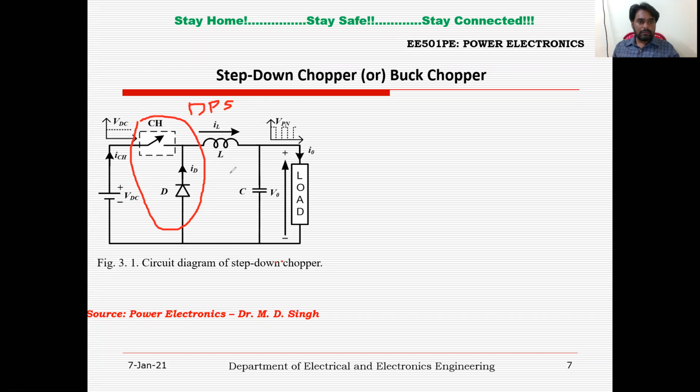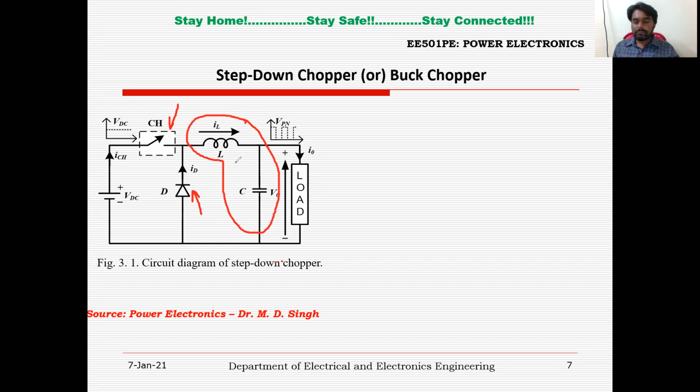In addition to this DPST switch, which is now replaced with the chopper and the diode, the circuit also has the LC. These LC components are called a filter.